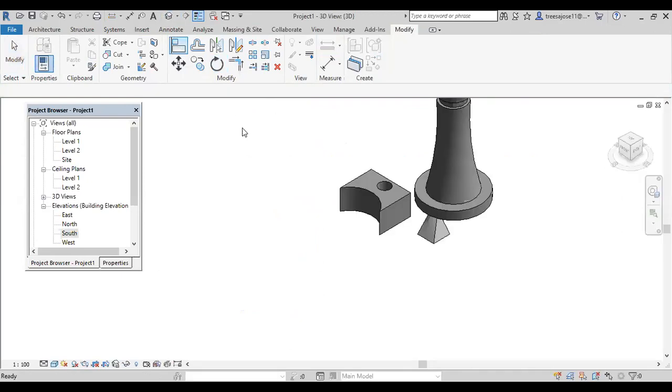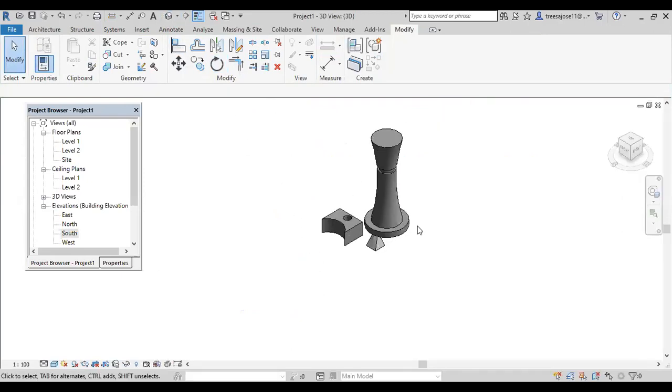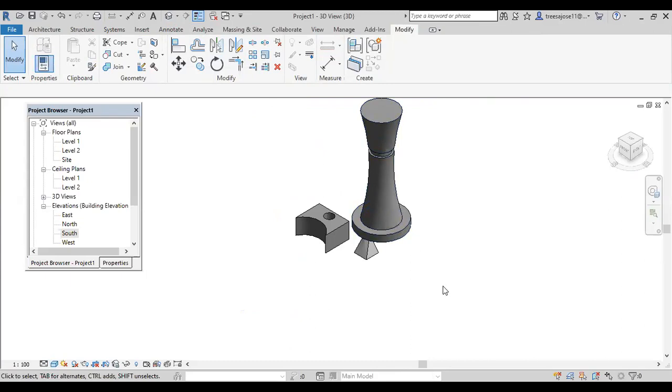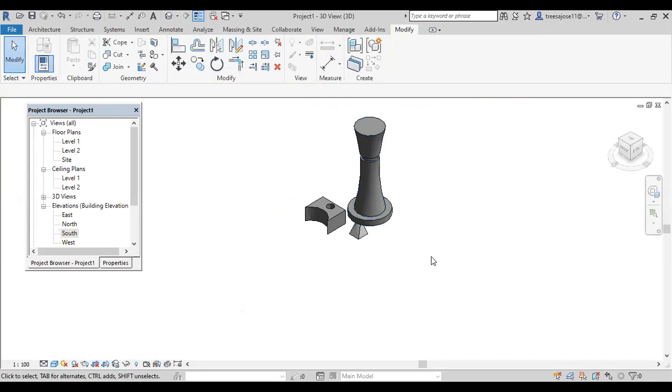Automatically the revolve will be there. Okay. So I need that in this position. That is why I have created that reference plane. It is not compulsory for the revolve command, but the reference plane is an important factor. The motto of creating that reference plane is that I need the model in that position. That is why I use the reference plane. This is the revolve command. Okay, the condition is first you finish the profile. After that, you have to input the axis.